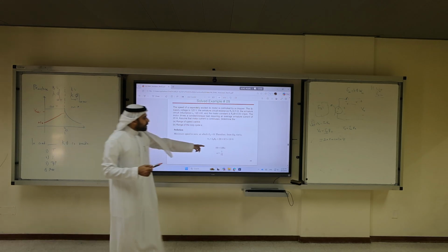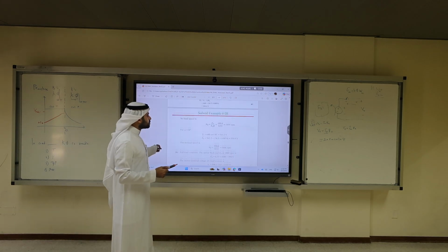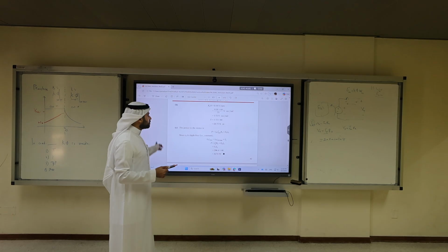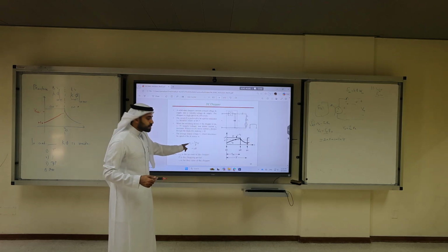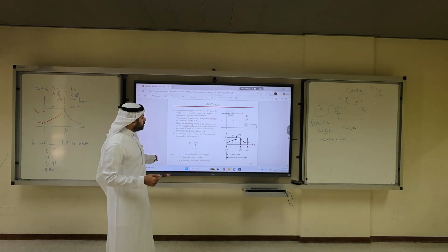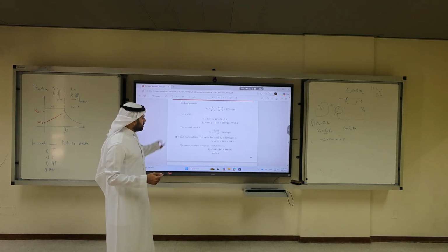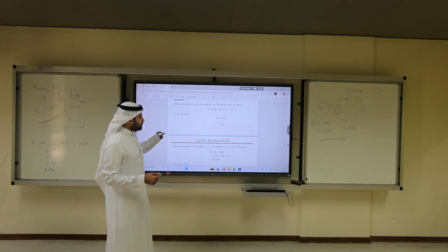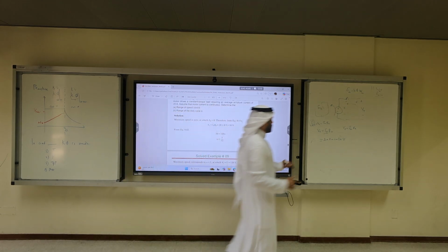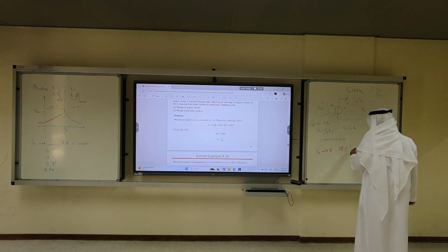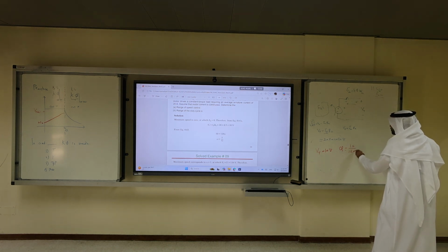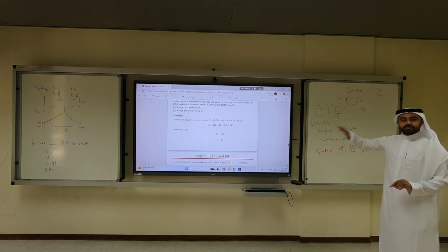So what is the value of alpha for the chopper? Alpha is T on over T. Is it 10% of the supply? No, it's 10. Is it 10 or 12? It says 1 over 12. Because VT equals 10 volts, alpha equals 10 over 120, which is 1 over 12. This is the minimum.